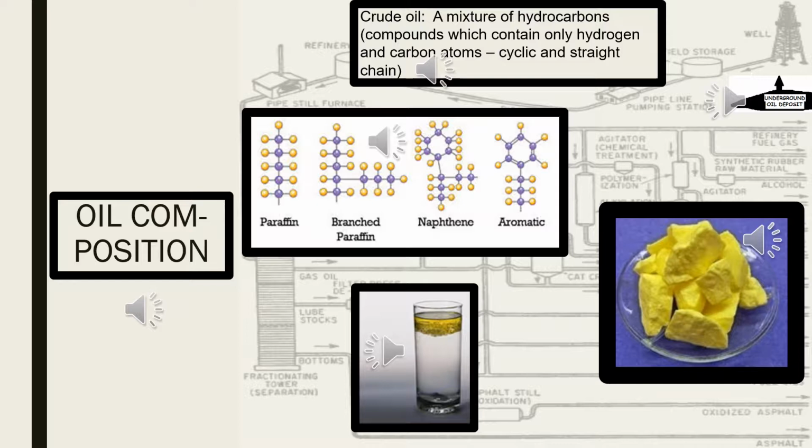Crude oil is also characterized as sweet or sour depending on the level of sulfur, which occurs either as elemental sulfur, or as compounds such as hydrogen sulfide. Sweet crudes have sulfur levels of 0.5%, or less, by weight, and sour crudes have sulfur content of 1% or more by weight. Generally, the heavier the crude oil, the higher its sulfur content. Excess sulfur is removed from crude oil during refining, because sulfur is oxidized during combustion of oil and released into the atmosphere as a major pollutant.